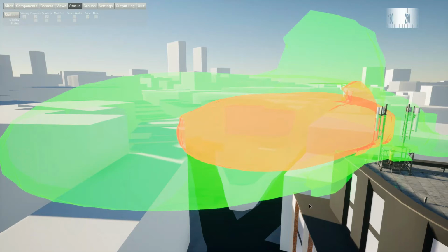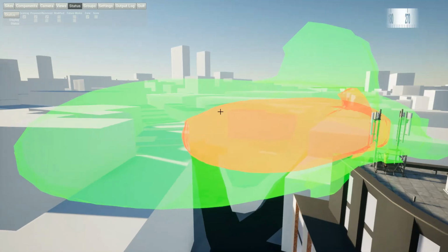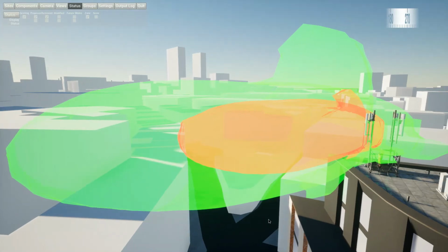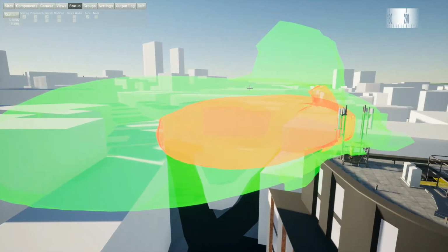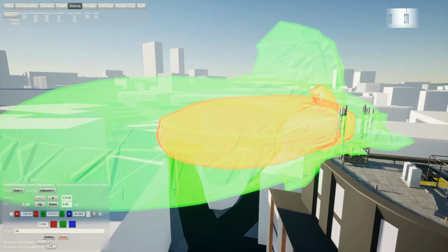And for the calculation, customers have two principal options. One is to use the AmbiFlow calculation for the ICNIRP, in which case the tool will fetch all of the antenna positions, all of the power and the other parameters, dispatch all that information into the tool and generate these two surfaces, the occupational and public, into the scene.